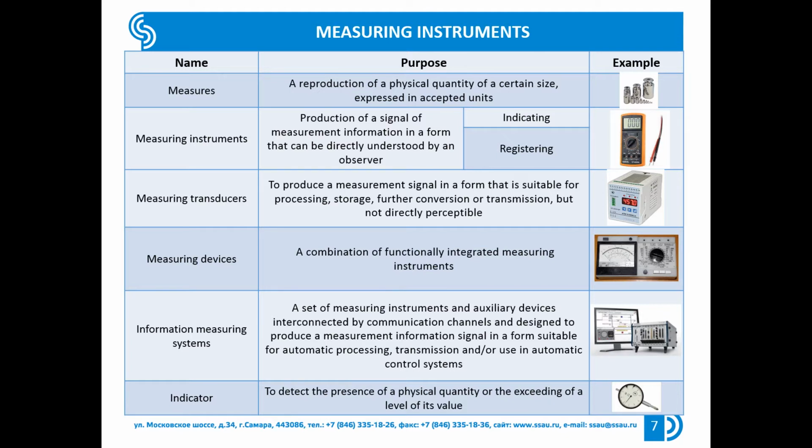A sensor is a structurally isolated primary transducer from which the measurement signals are derived. The part of the primary transducer that is directly influenced by the measured quantity is called the sensing element. In recent years, the term sensor has been used to denote a sensing element with a minimum group of transducers. Measuring devices and transducers are named according to the type of the measured quantity: thermometers, thermal converters, manometers, pressure transducers, flow meters, flow rate transducers, etc.